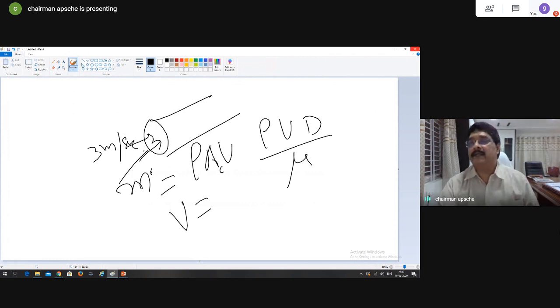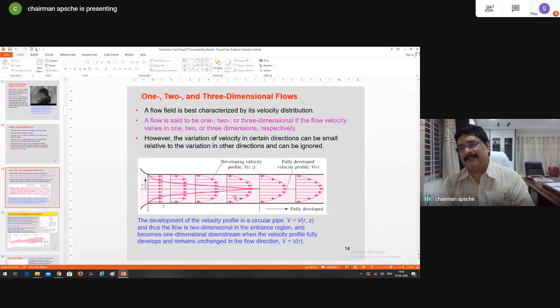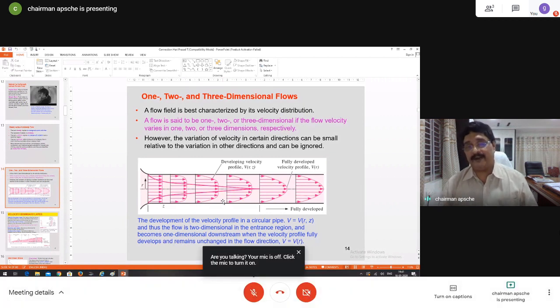So with this, I have probably explained turbulent flows through internal flows. What is that? A developing flow, fully developed flow, velocity profiles in that. What if it is laminar? What if it is turbulent? Critical Reynolds number is 2300 and characteristic dimension is 4 Ac divided by wetted perimeter. And I also said the fluid properties are taken at bulk mean temperature. What is bulk mean temperature? It is the average of plate and average fluid temperature: Tw plus (Ti plus To) divided by 2, whole divided by 2. Okay, that's all.